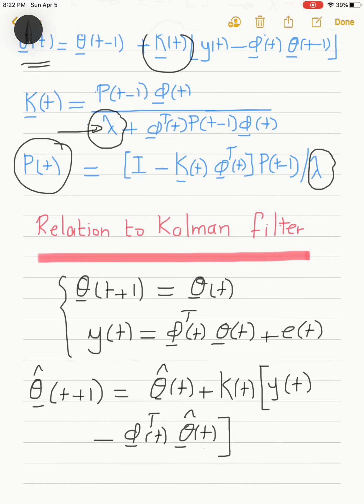So if we carry out this setup, what we get would be again the equations of the recursive least squares. Gain k would be calculated as we have seen in the recursive equations, and in that case the recursion starts with assuming some initial distribution with mean theta of 0 and a covariance matrix P of 0. So the initial covariance matrix would correspond to the covariance of the initial estimate of the states.